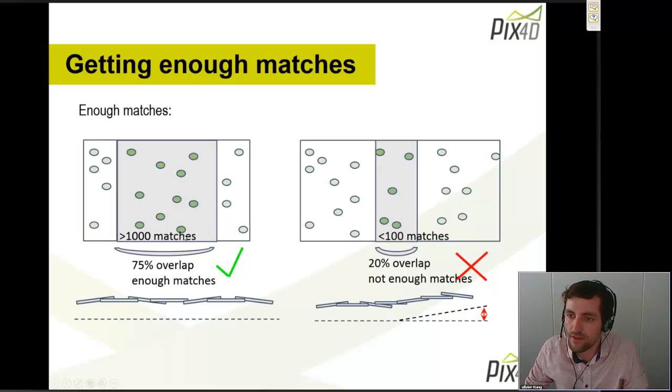And again, with a camera in the range of 20 megapixels, this usually accounts for an overlap of 75% between each image. So let's summarize. By computing a huge number of key points, we are able to model a lot of imperfections and to correct for them and to have very good results with a consumer-grade camera.